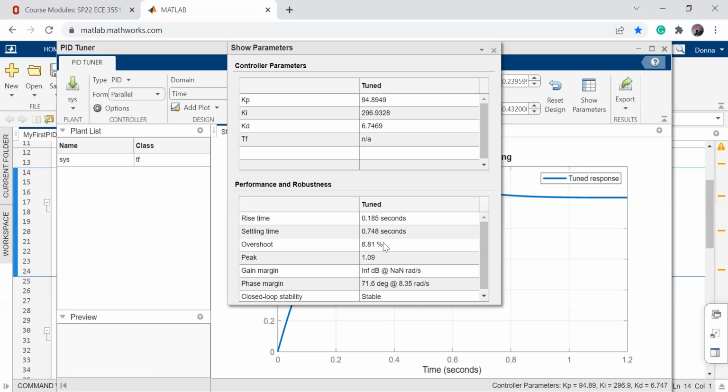It depends on your system, your project, your system sensitivity, so you need to do a little research. What is the common engineering in the field that you're designing a controller for? They all decide how much. For our assignment and exams, if the condition was 2 seconds, go maybe 10% below, really your judgment. Whatever you put, you'll explain why. So if you go with 1.6 below 2 seconds, you'll say that I assumed this much threshold and the tuning was not difficult.